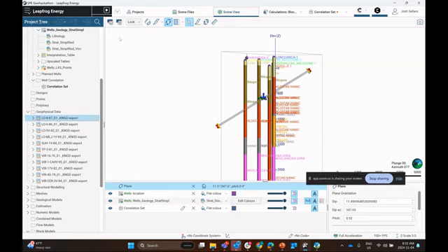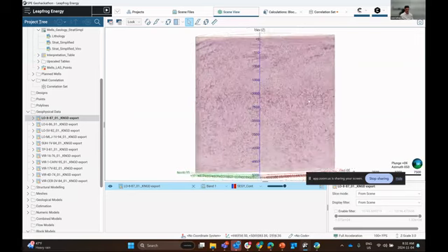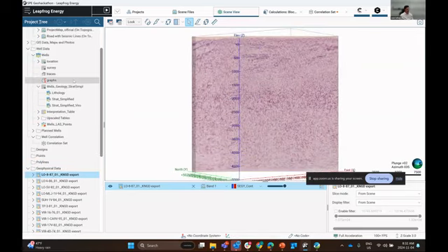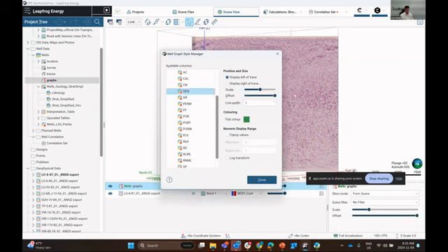All right. Another question is whether the logs of wells with a seismic section or line can be seen in a scene window. Yep. So if you have a seismic section like this and you wanted to see logs associated with your drilling information, you can drag in the graphs object and we can choose, maybe let's choose the density logs.